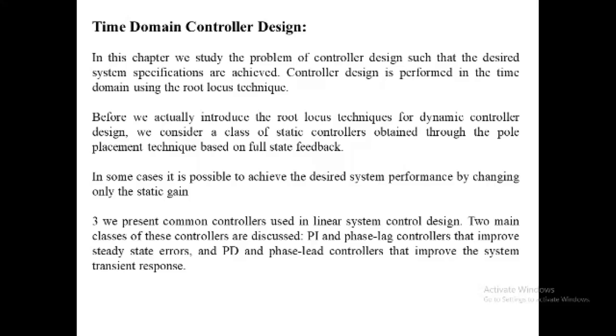Combinations of these controllers, which simultaneously improve both the system transient response and steady state error, are also considered here. A simple class of dynamic feedback controllers can be obtained by feeding back the derivative of the output variables. These controllers are known as rate feedback controllers and are presented in this section.